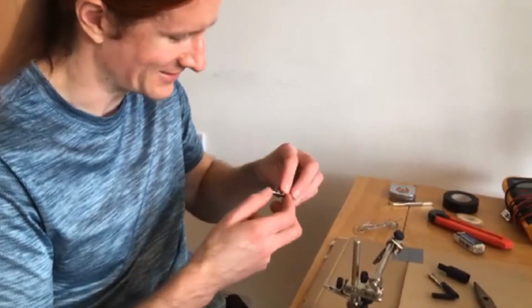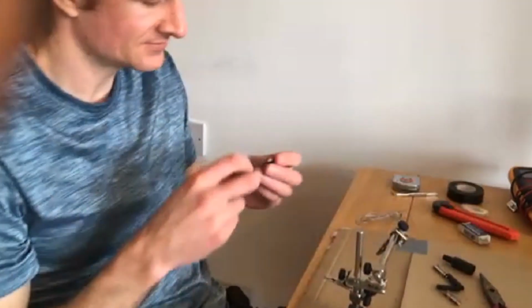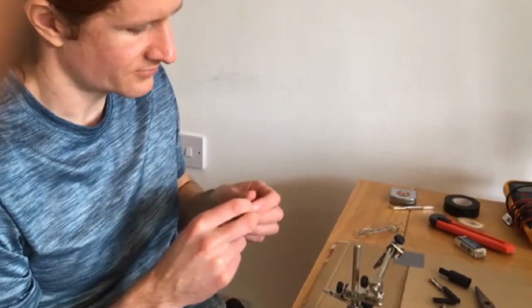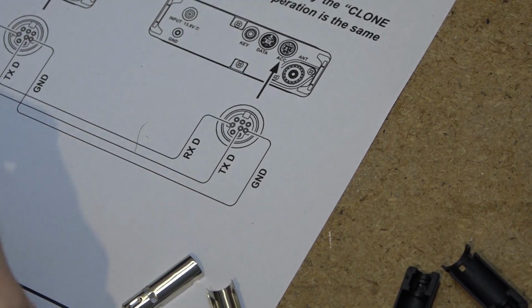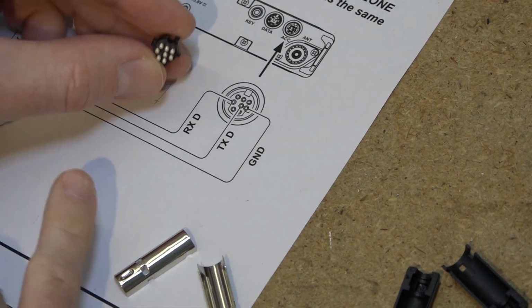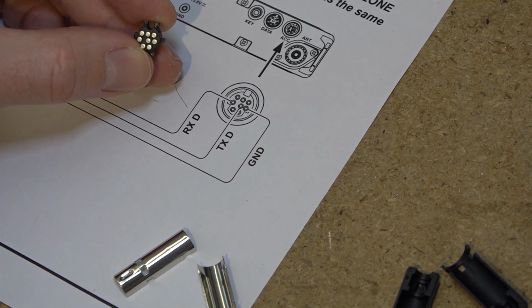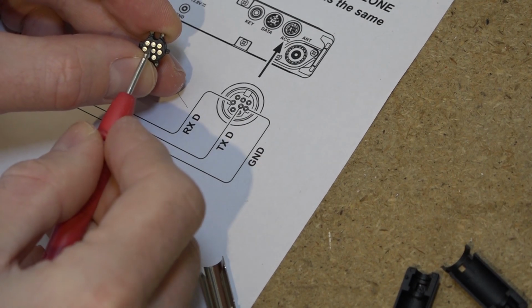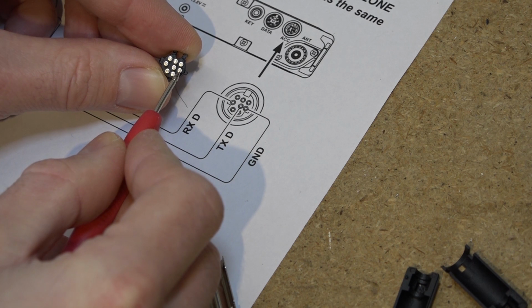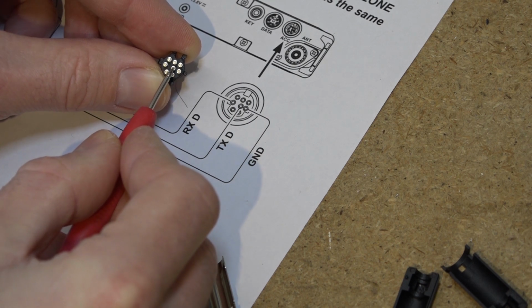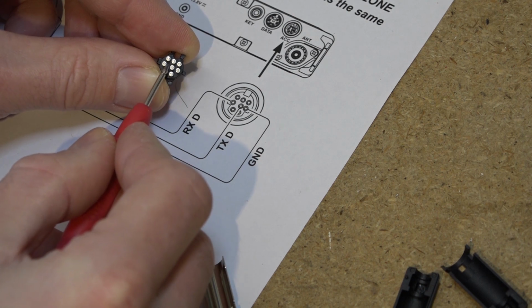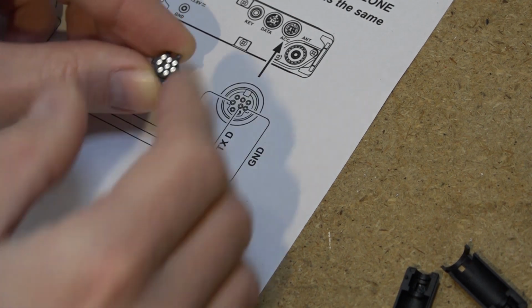Now we're going to want to prepare that in the same way as we did the wires. So we're going to want to tin that. And if you look back at the diagram, we're going to want this held with the 3 pins at the top. You're going to want to tin the middle row of 3 connectors here. So you're trying not to get any blobs of solder that might cross over between the different pins. You just want to tin those 3.